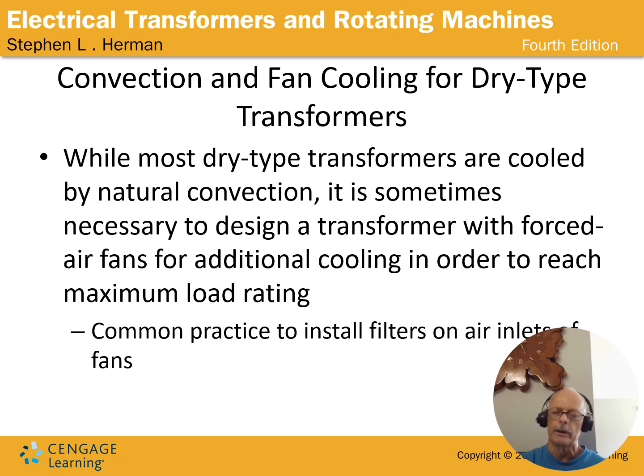I've seen people get lit up pretty hard for that. I've done it myself a couple of times changing out contactors, but always make sure your power's off. Shut the power off, check it with your meter, check your meter to make sure it's good, and then go brush everything down.